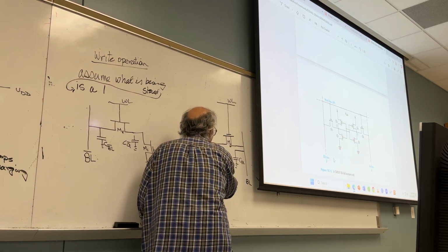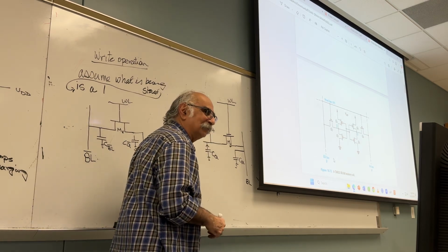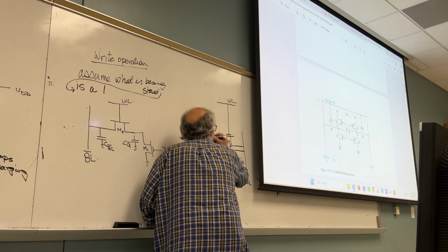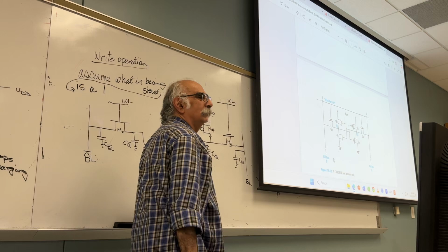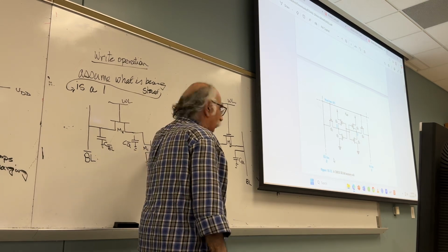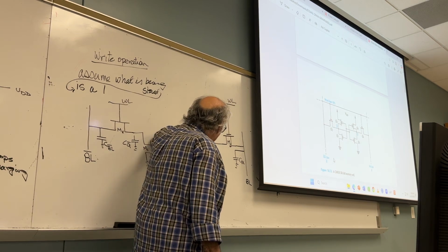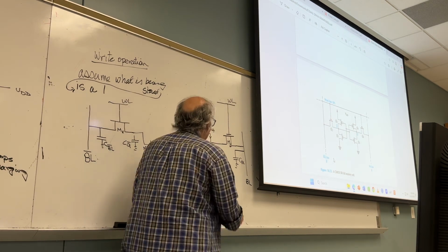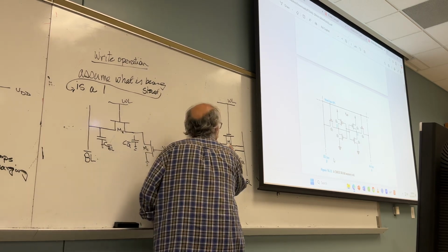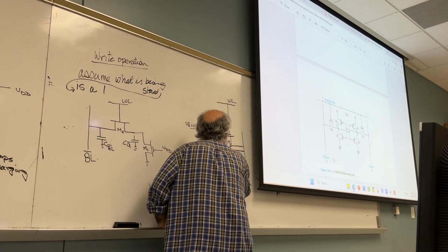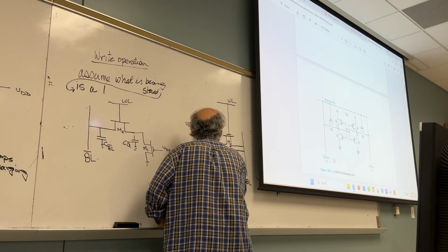It will begin to discharge. The current will begin to flow this way. You follow me or not? Yes. Okay. Then this one is also on. Why is this one on? Can you tell me why is this one on? Q bar equal to 0. So there is a current here, there is a current here, and the current will come here. So this is I6, this is I4, this is ICQ.